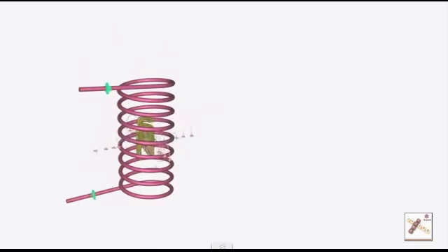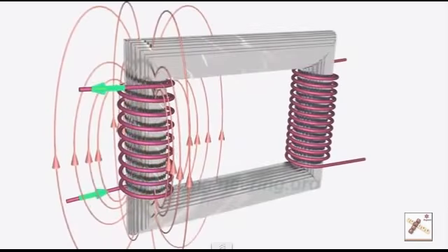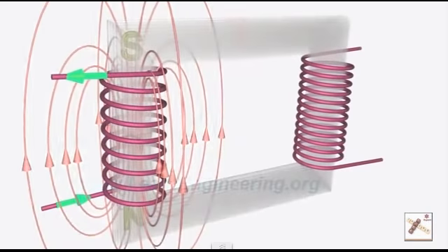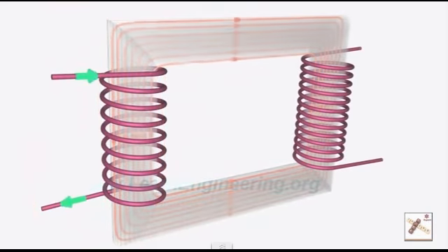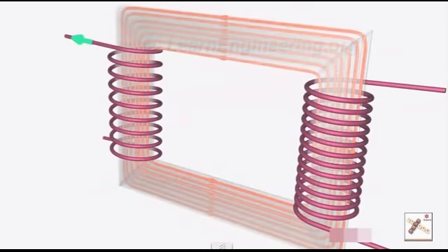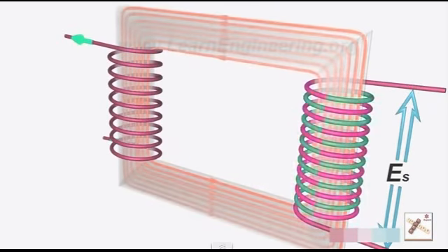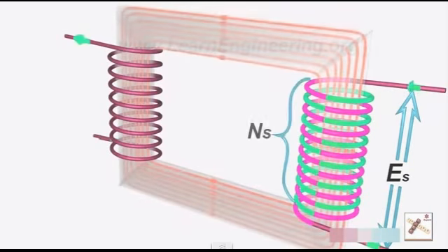This magnetic flux can be effectively linked to a secondary winding with the help of a core made up of ferromagnetic material. This fluctuating magnetic field will induce an EMF in the secondary coils due to electromagnetic induction. Since the turns are arranged in series, the net EMF induced across the winding will be the sum of the individual EMFs induced in each turn.